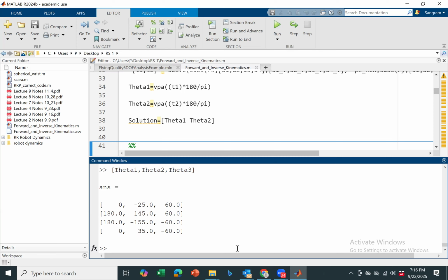This is actually your assignment, and this also is your lab 4. So when you go to lab 4, make sure you have the script running, and the only thing you need to do is make sure your robot axis and the kinematic diagram axis are aligned, punch in the values, get the number, take a snapshot, and you are done with your lab.